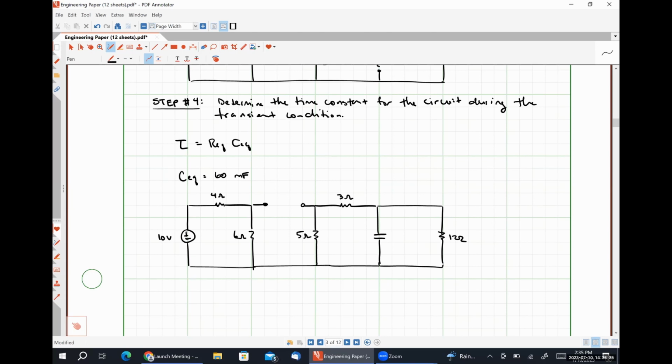We are trying to find the Thevenin equivalent resistance with respect to our energy storage element. So that means I take my energy storage element, in this case, my capacitor, out, and I'm looking in through the terminals behind when I remove that energy storage element. I also need to be looking at a dead network, which means I turn my independent source off.